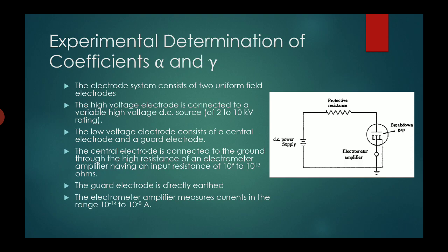The chamber is evacuated to a very high vacuum in the order of 10 to the power minus 4 to 10 to the power minus 6 torr. First, all the air inside the glass chamber is taken out, so that you have a very high vacuum of 10 to the power minus 4 to 10 to the power minus 6 torr. Then it is filled with the desired gas and flushed several times till all the residual gases and air is removed.